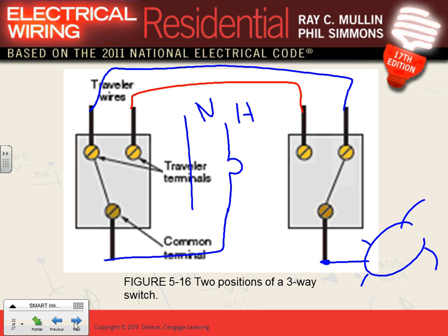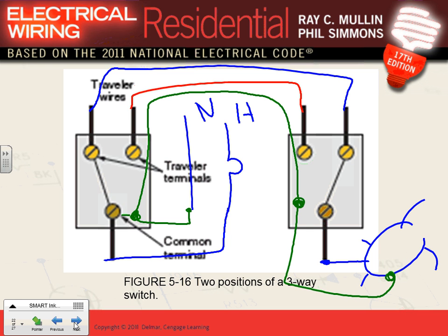So I brought my neutral. Now, Jeff, do I have a neutral with this switch? Yeah, Chad, good to go. Then I'm going to go from here through with the cables and come here. Do I have a neutral, Jeff, in the second switch? Yep, Chad, I do. Then you're going to come from here to here. Now, do I have a neutral with every switch? Yep, I do. Here's cable number 1. This will be 14-2. Cable number 2, this cable would be what in this case?